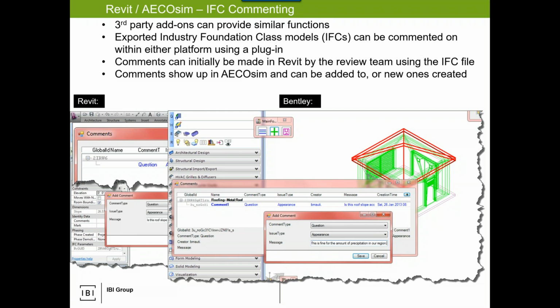And that taxonomy is guaranteed to be able to move into different software vendors. The challenge is when I go from Revit, EcoSim, ArchiCAD, etc., to IFC, I'm by default saying, I hate saying dumbing down, but I'm lowering the extent of the geometry and the information to be compatible with the taxonomy of the IFC file. And then once I'm compatible, I'm open everywhere.